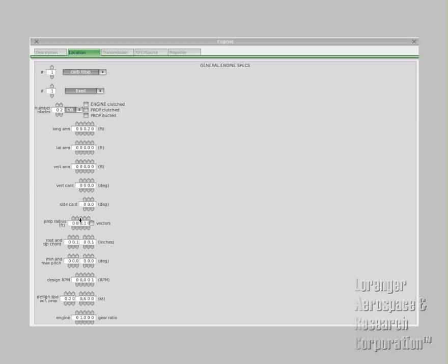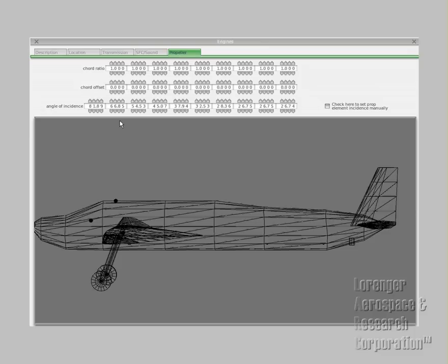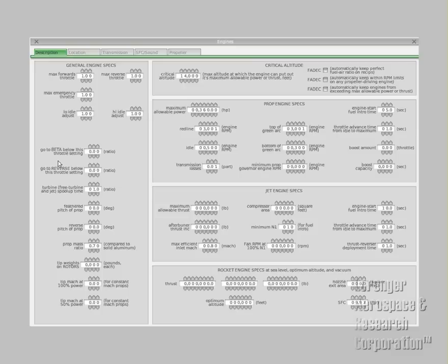And in your engine, you're going to change this many, many times. The propeller here is a quick rubbish scenario. You never want to do this, and your design RPM is just ridiculous at 4,000. It shouldn't be that. It should be 2,700 RPM, typically, especially for a propeller-driven aircraft. That's generally the ballpark, at least from my experience. And in here, there are a lot of things you can mess with, but you can get around that later. Again, we're making a simple design that flies.